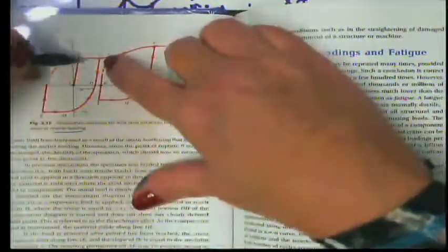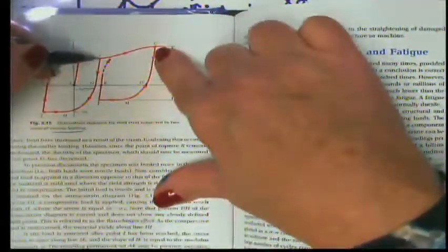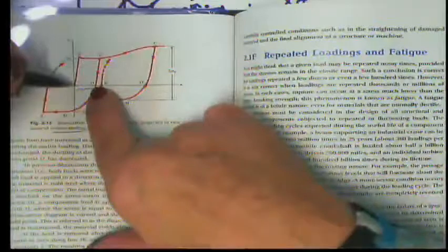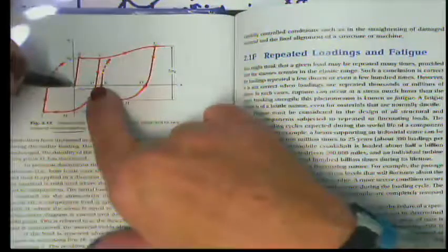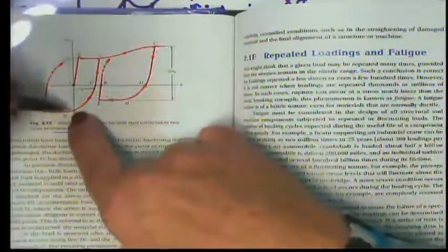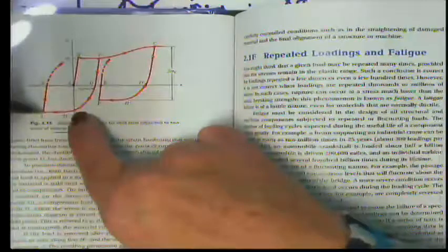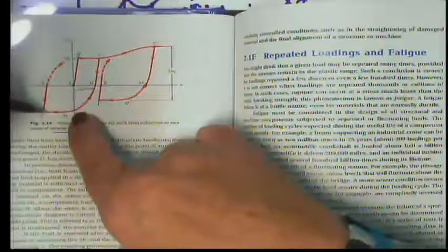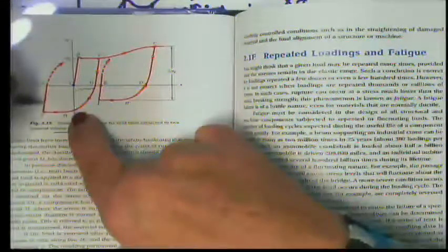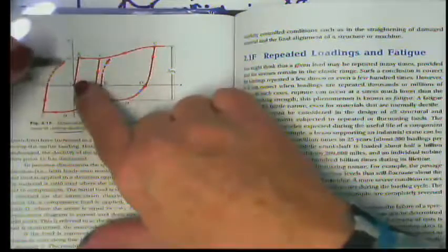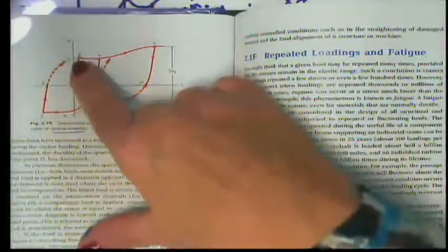This curve indicates that we get into the yield range. We don't get into the strain hardening range. We just get to the yield range. We remove the load, and once again, we have an increase in length because we have allowed the material to yield. But then we take the load back to a negative, and we continue. We have sort of this strange behavior where the material continues to shrink without really removing very much of the load. We just remove it a little tiny bit, and then we remove the load completely, and we have a shortened material because of this cycle of loading. And then if we increase the load, once again, we have a rupture at a value below sigma yield.